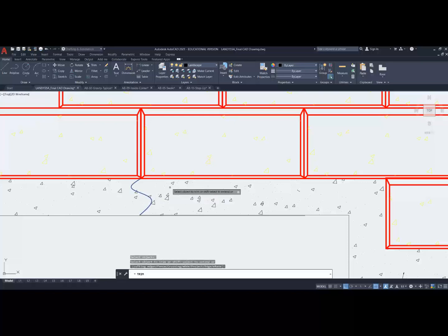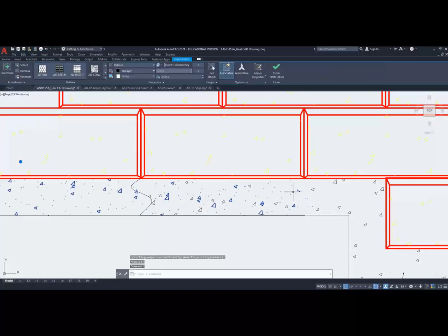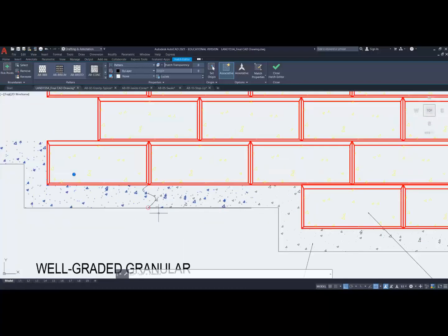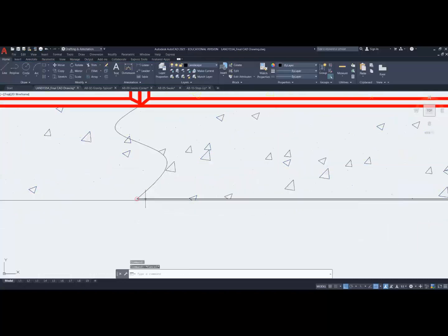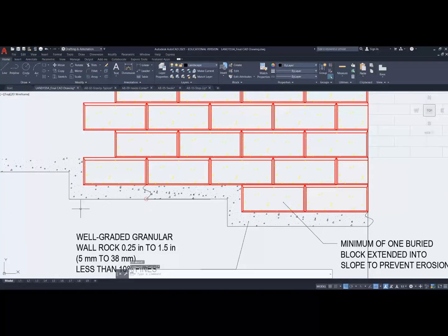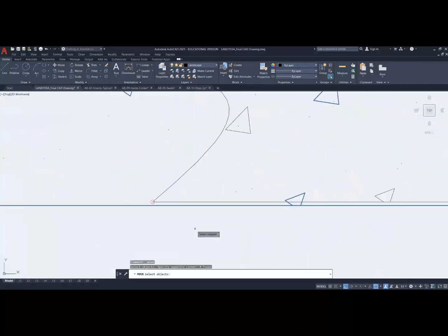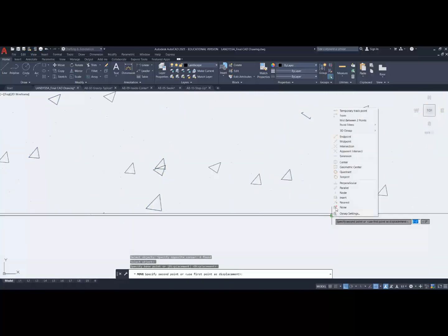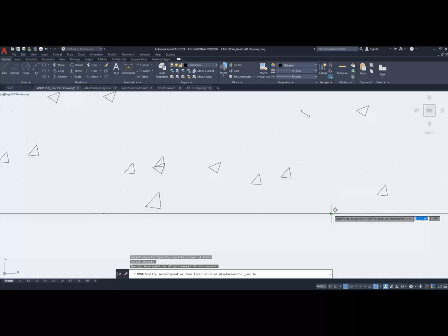See, I've got a couple of items here that are double hatched. See that? That hatch has gone all the way over here. Now, this hatch doesn't have a boundary edge. Not too sure why. And you can see after I copied and pasted, there's some inaccuracies with the drawing itself. So we can't really trust somebody else's work to be perfect. We'll work with it. But again, when I copied and pasted that, I'm getting a slight bit of inaccuracy. I'm going to move that up a bit.